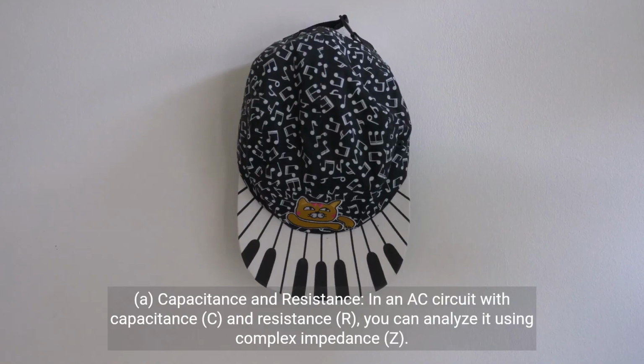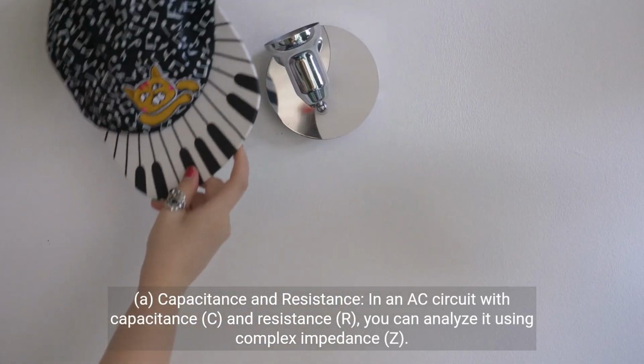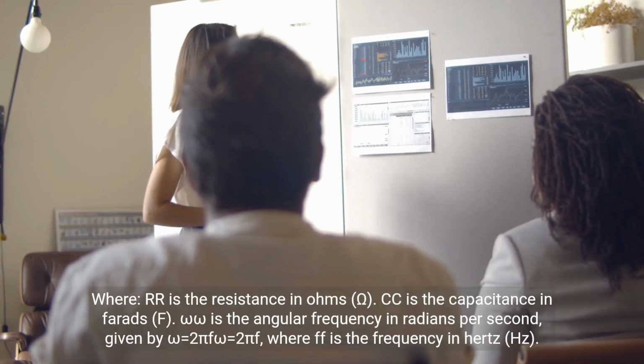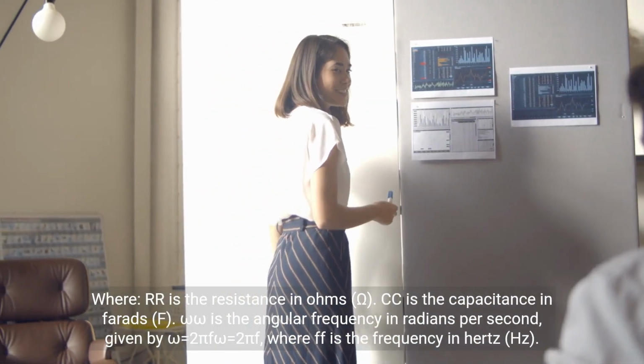A. Capacitance and resistance. In an AC circuit with capacitance, C, and resistance, R, you can analyze it using complex impedance, Z. The impedance Z in this case is given by Z = R - j/(ωC), where R is the resistance in ohms, Ω, and C is the capacitance in farads, F.